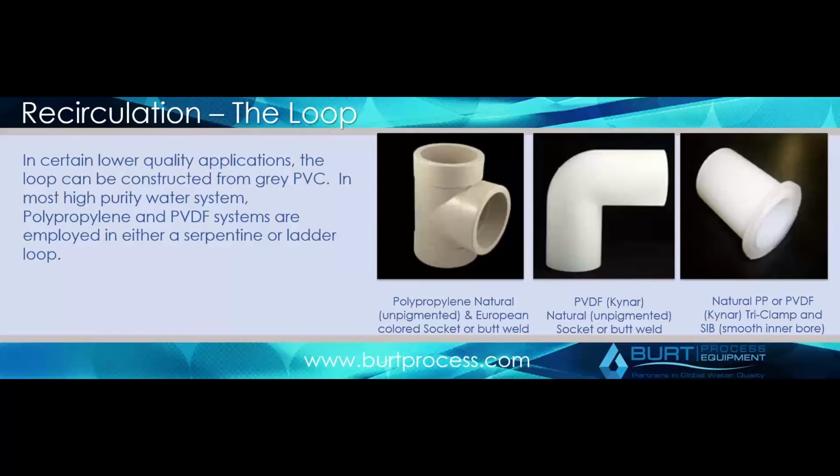And beyond being a typical butt or socket weld, what you're basically doing is you have a bladder in there which expands, which then allows for a very, very smooth, basically butt weld between the joints when you're talking about a sanitary thermoplastic system. And obviously stainless steel, which is always a sanitary system in those cases.